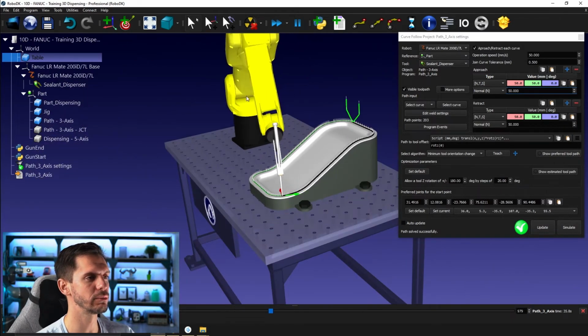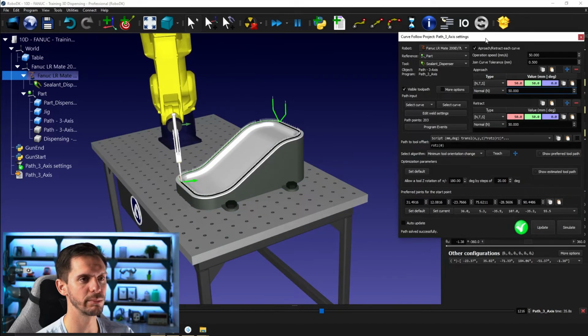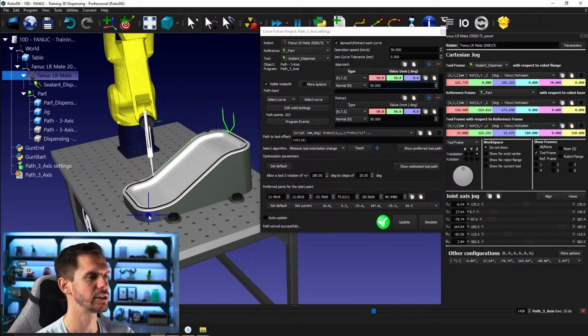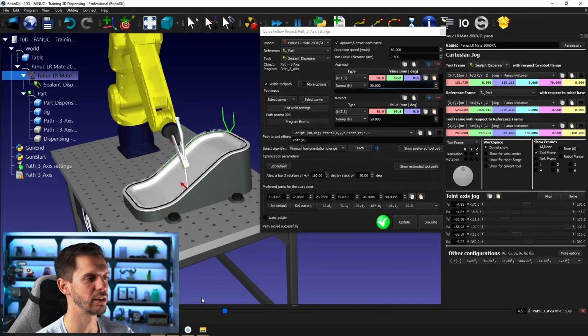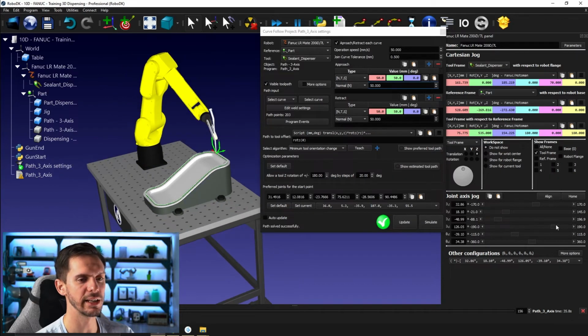Okay, so here, first of all, you see that we have a small rotation, mostly because we are potentially hitting a joint limit, joint limits of 4. So I should modify that by bringing back my robot to the starting point. I can say, okay, I'm too close to my joint 4 starting point, so I will make it like that here, like this here, like that here.